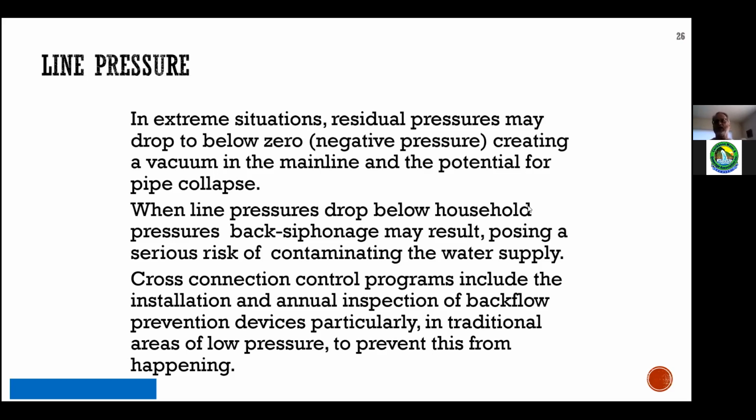So picture a subdivision on the top of a hill. And at the bottom of the hill, there's a fire hydrant, and the city crew comes to flush the water main, and they open up the water main, the pumper port, 4.5-inch port, full blast, and then next thing you know, the office is getting a bunch of phone calls from those houses up in the residential area saying, we got no water. That's the energy that has gone negative, because they're now basically like the tide going out. They're stranded and have no possible way of getting positive pressure into their system.